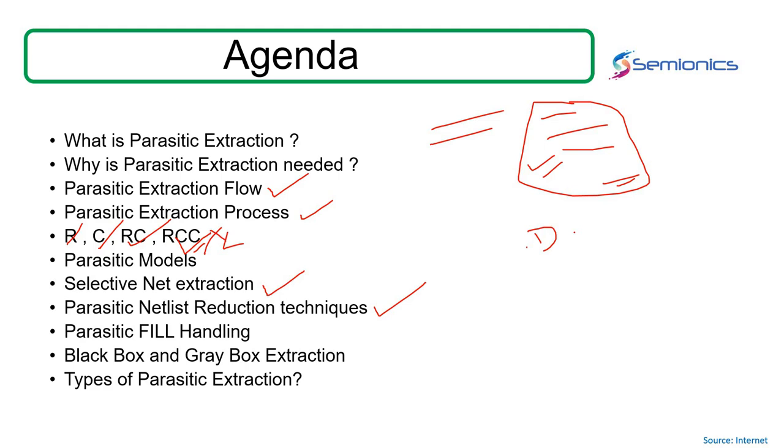DSPF, that is the detailed standard parasitic format, is the file we dump after we do the parasitic extraction. I'm mainly mentioning the analog designs over here. Likewise, for digital, we've got SPF, and you would again process it and convert it into SDF as well.